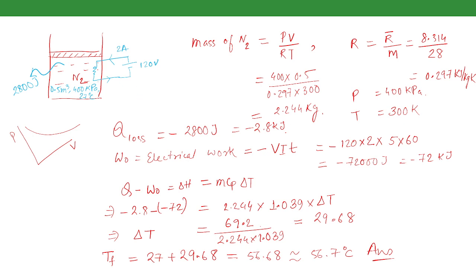So if the pressure increases to 401 kilopascal, this 1 kilopascal increase will result in an increase in the volume. This increase in volume will cause a decrease in the pressure again, say minus 1 kilopascal. This decrease will keep the pressure constant at 400 kilopascal. That means had this piston not been movable, it wouldn't be possible. If it is not a movable boundary, it is never possible to maintain a constant pressure process, because in that case the volume is constant, right? Yes, the volume is constant.